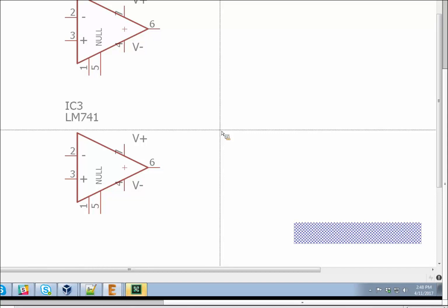You won't see too many crazy things. I've seen, for example, transistors generally are Q's, but even then I've seen some people use T's for those. So in general, there is some pretty strong conventions, but they're not written in stone like some other aspects of ECAD are. So you could use whichever one your team will understand best. Most people can tell IC and U, and they can follow it. I hope that answers the question.